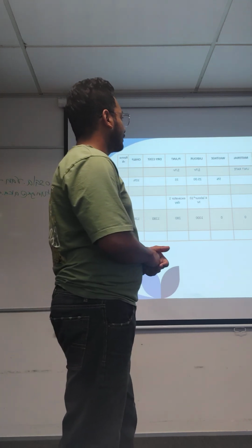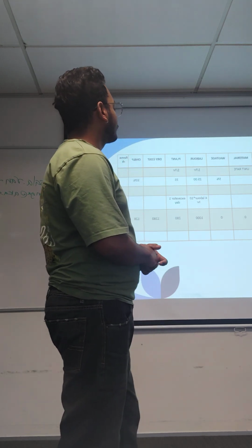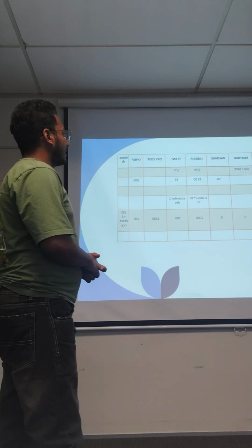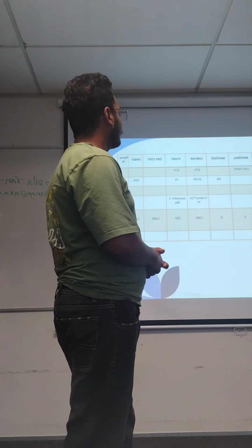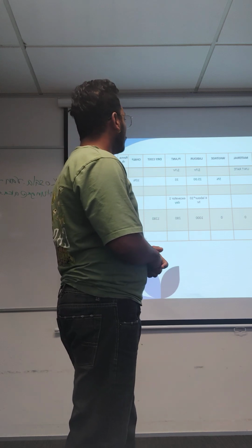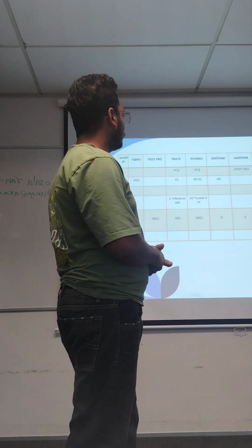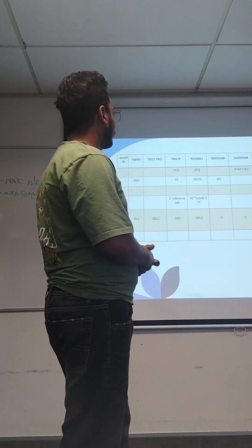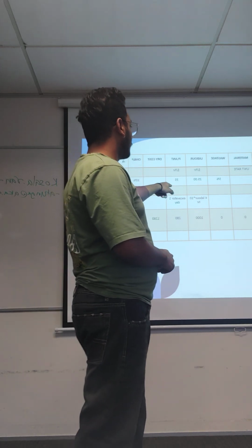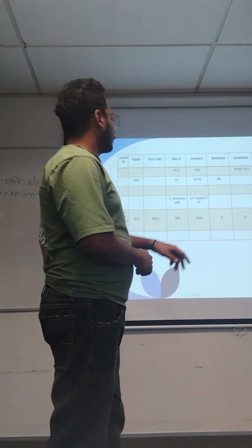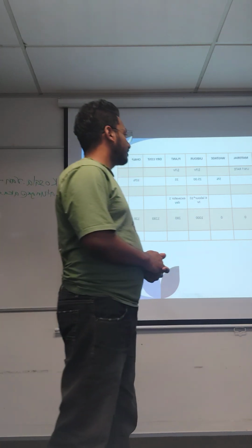This is the spreadsheet: substructure, unit rate and the labor hours. Wastage is 5%, as I already told you. Labor is 25 dollars per hour, and plant is 35 dollars per hour. So it's all the earthwork, and 4 labor use 10 hours. This is the calculation shown in the spreadsheet. Next one.